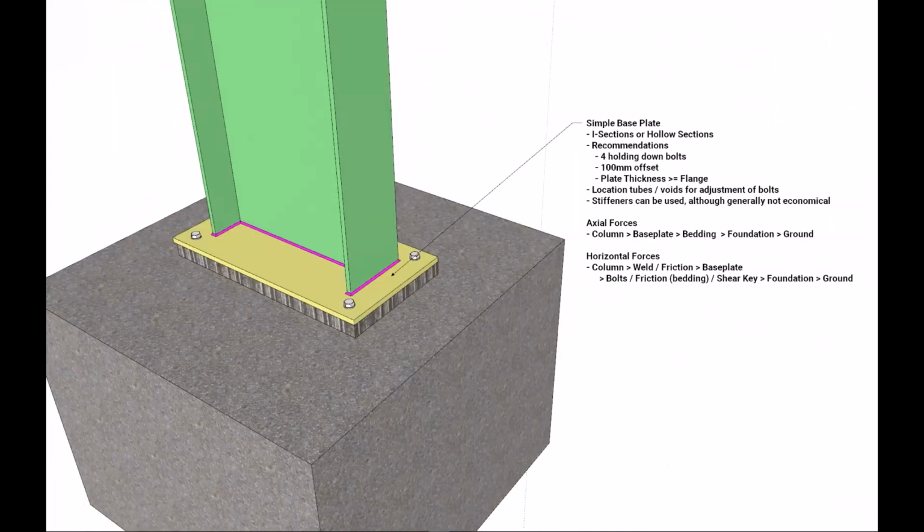Now, next, we'll look at a simple base plate. The software can design base plates for columns of open I sections and rectangular, square, or circular hollow sections. And just some normal practice in the UK: holding down bolts are cast in place with an arrangement of 4 bolts as a minimum, irrespective of whether the base is assumed to be pinned or fixed, and they're placed typically outside the extent of the section, and that will ensure column stability during erection stages, where single columns may not be tied back to temporary or permanent bracing.